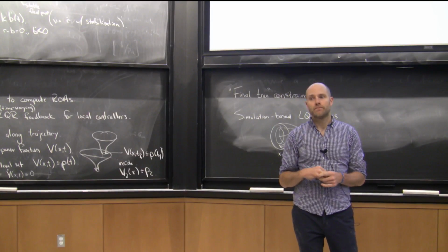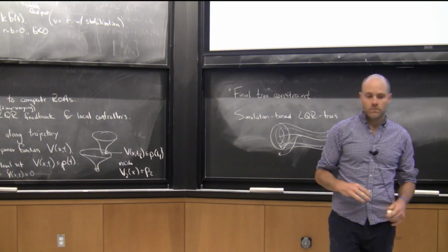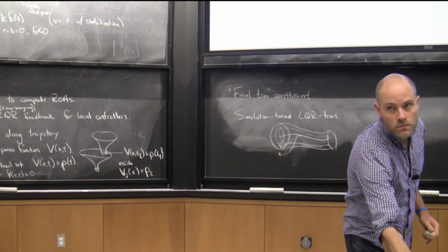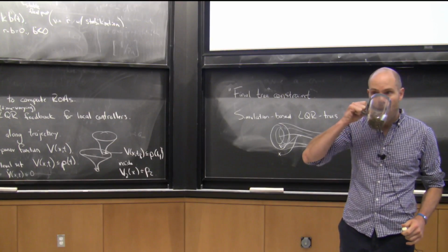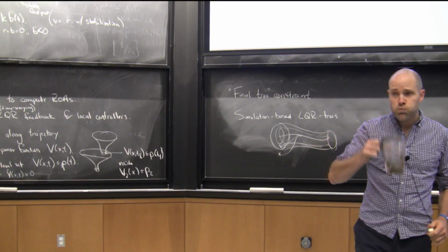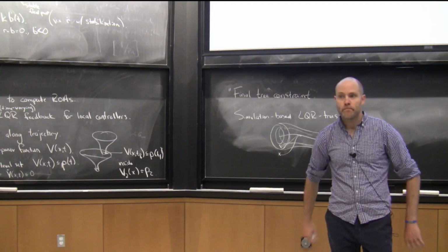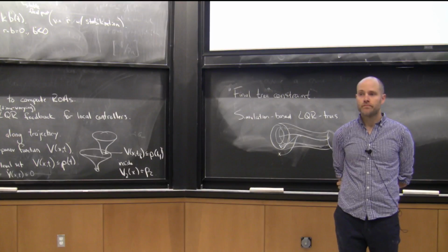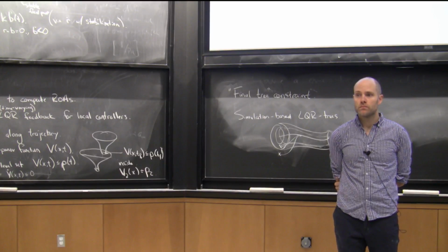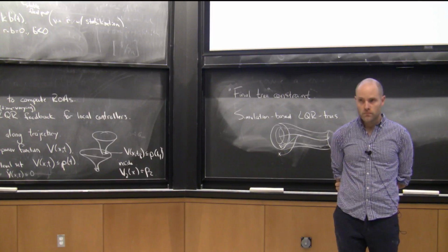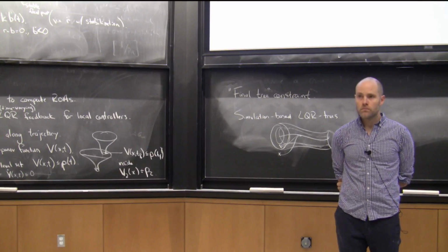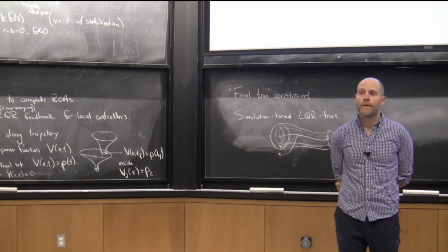Can't you get a pretty good approximation? Suppose for simplicity that your world only has 5 different kinds of cups and you're only trying to estimate which type of cup it is, and you have some sort of model of your perception system: given that this cup is identified by our perception system, the probability that it actually is this cup is this. That's really similar to your pose estimation uncertainty. So should we be able to do it if you had this model of, given this identification, what the object is, and then that can be tied to the pose based off of the volume of the object.